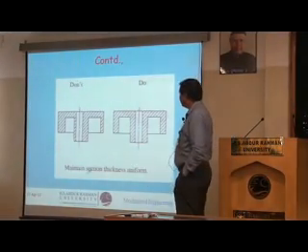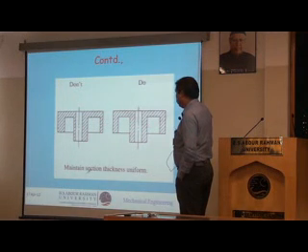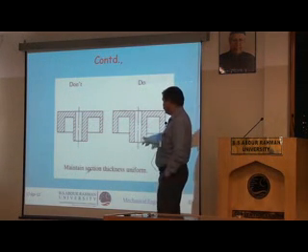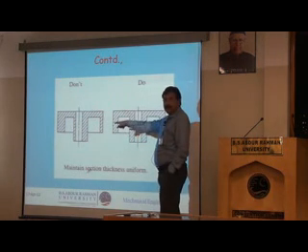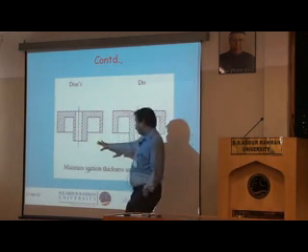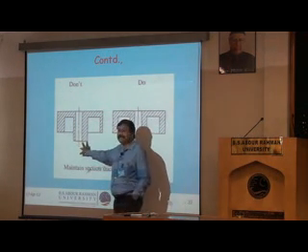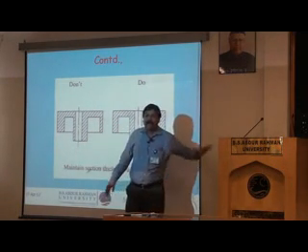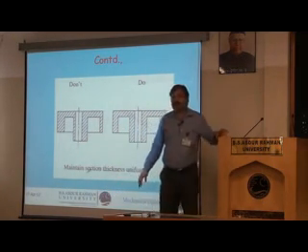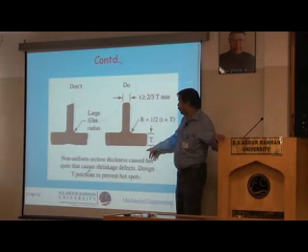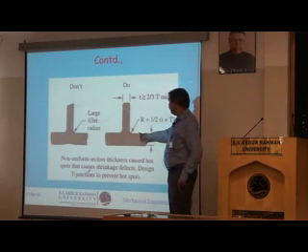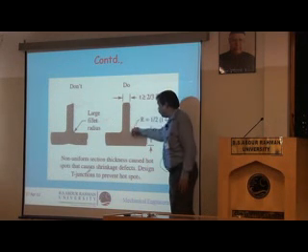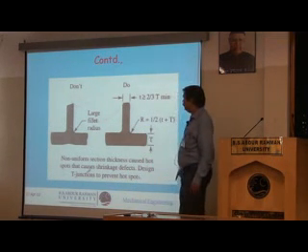Next please. So here again the section thickness is to be kept uniform. You have a very small thickness here and a very thick section here. It is not good because that will lead to uneven solidification and associated problems. Next slide please. So again, a large fillet radius is always preferred. A liberal fillet radius is required.